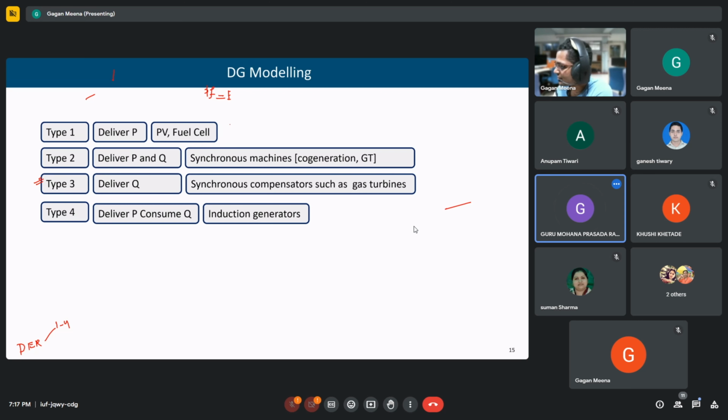Okay, sir. The same thing we are doing at residential. These industrial consumers are also doing the same thing. Because they are consuming more reactive power, their power factor is reducing and voltage is also reducing sometimes at that bus. So locally we supply that reactive power. So voltage is also maintained and power factor improves. Because voltage reduces because a large amount of current is drawn, so losses increase, so the voltage also reduces. So all these things we can avoid by using compensation.